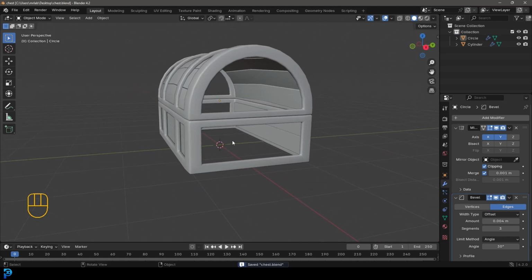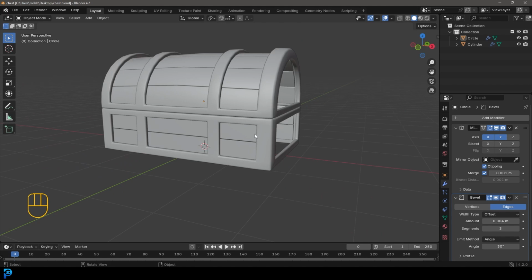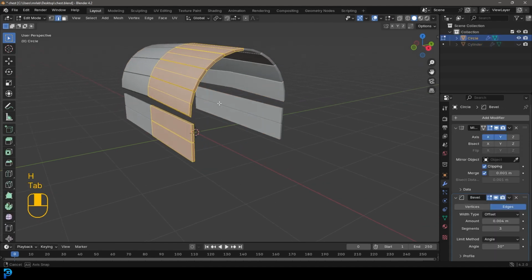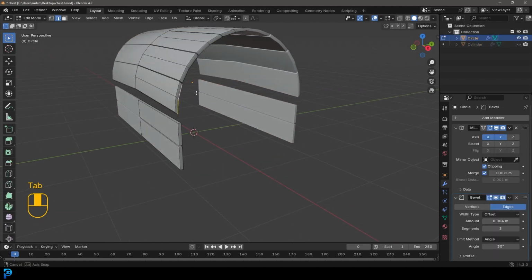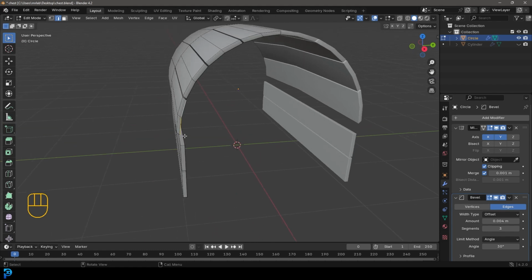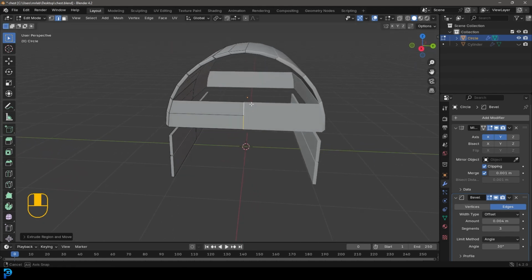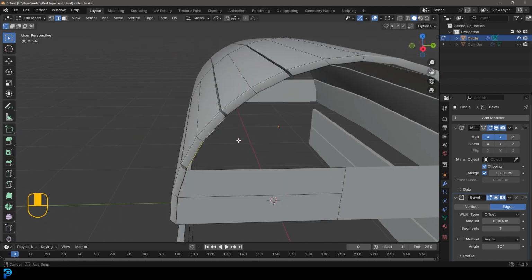Okay, and now with the side panels here, let's just keep that as simple as possible. I guess I'll just hide the frame for now by selecting it and pressing H. I'm going to grab the wood panels. I'm just going to grab this one and this edge here, these two edges. Shift D to duplicate, and then with them both active, I'm going to go E to extrude and Y till these two fuse.